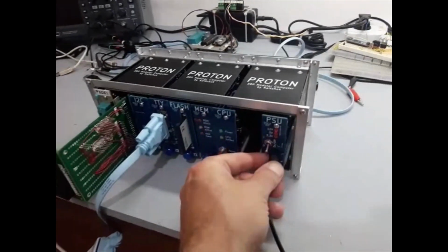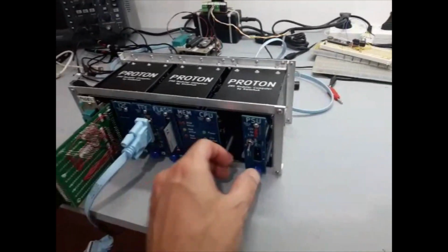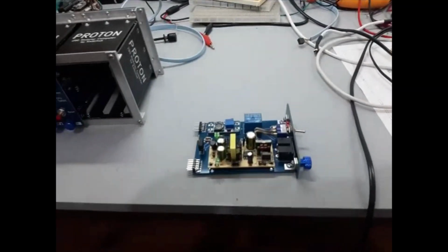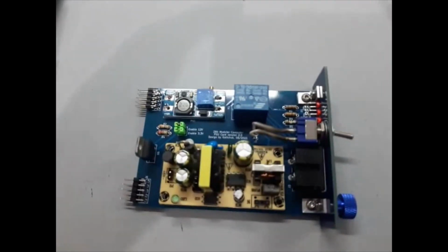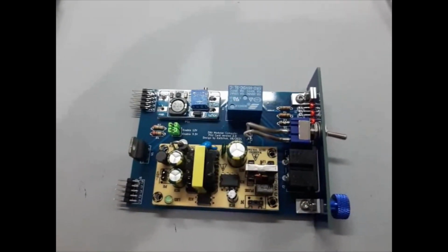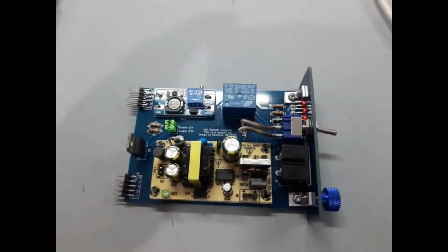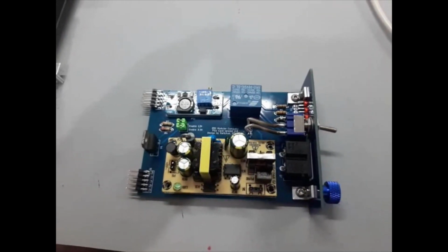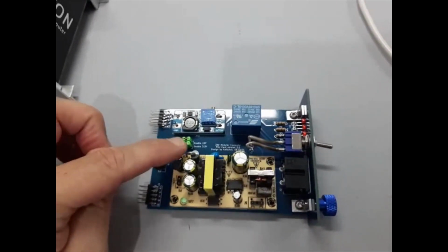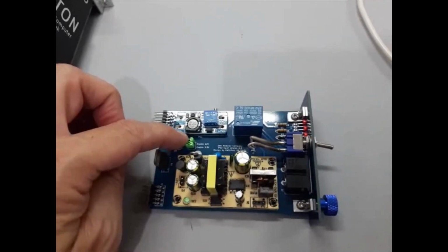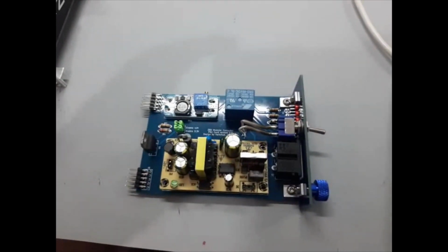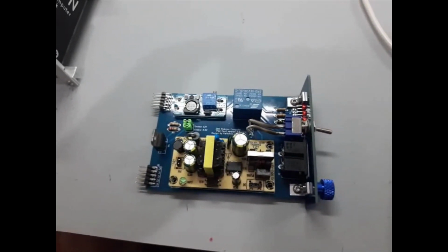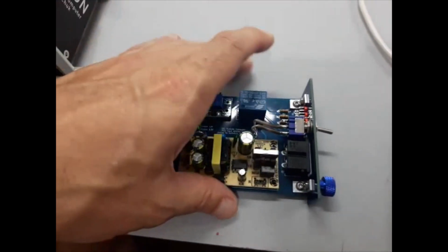Starting with this one. Take out the power cord. This is the PSU, which is the power supply unit. This card provides the 5 volts for all the other cards. Besides that, it provides also 12 volts and 3.3 volts. These other 2 voltages can be selected here, enabled or disabled here. So if you don't need 12 or 3.3 volts, you just take out the jumper and no voltage.